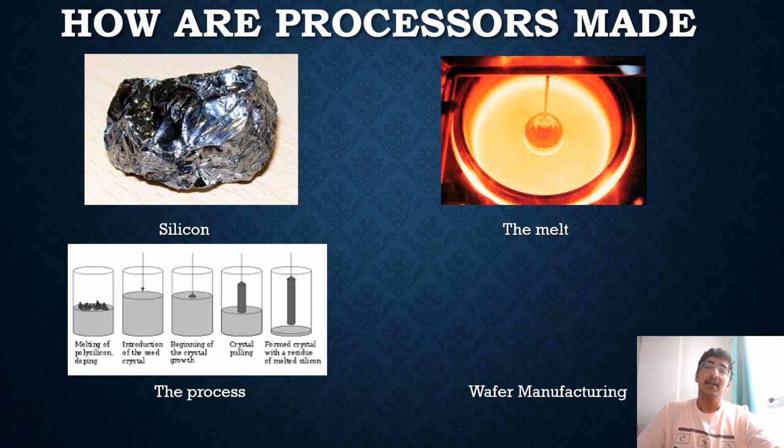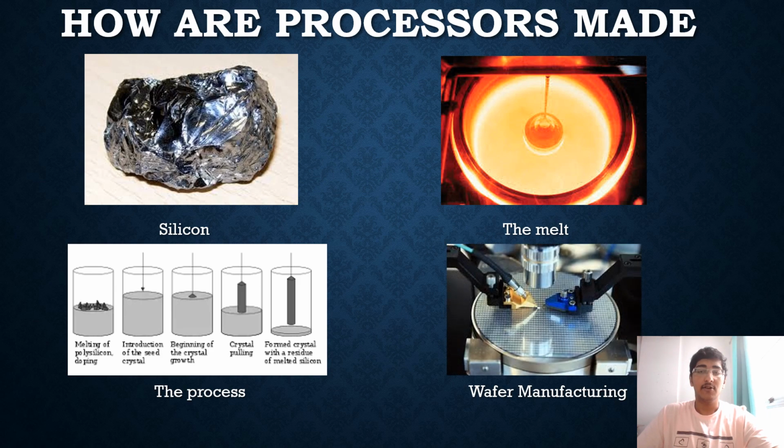So the ends of the bullets are cut off as they are the most impure part of the ingot, and so we get a pure cylinder. Now a cylinder is basically circles stacked upon each other. So we take the ingot and cut circles using some fine sharp saw blades, and they're cut in circles to avoid any chipping or cracks in them.